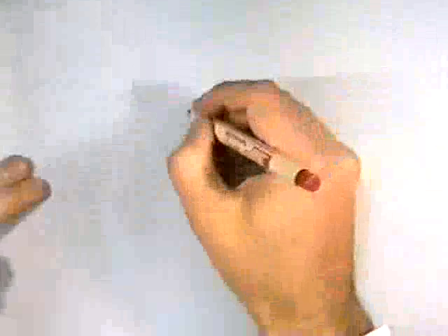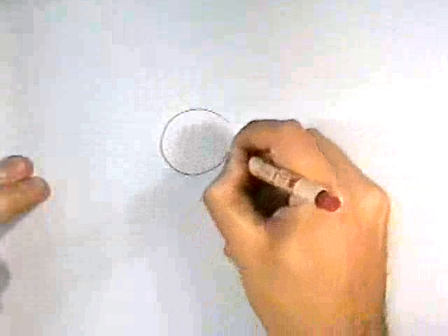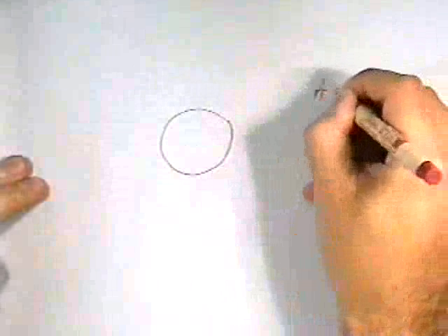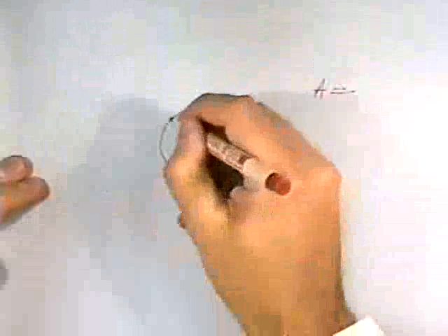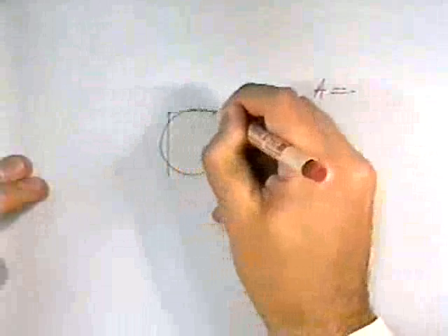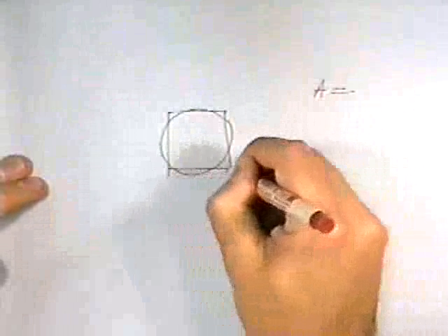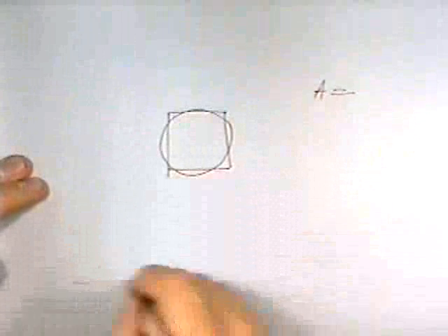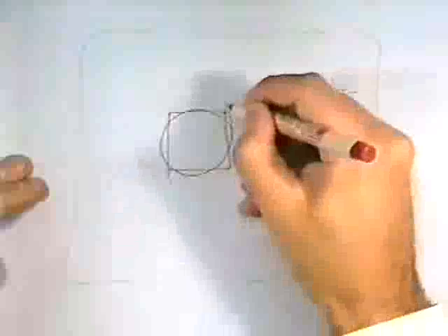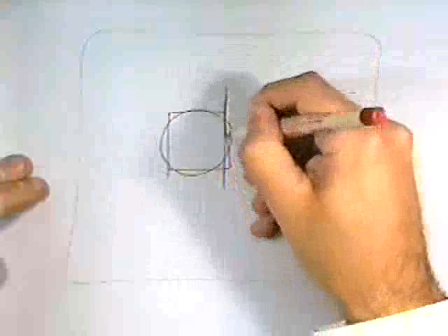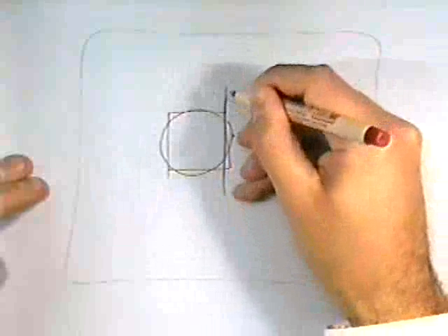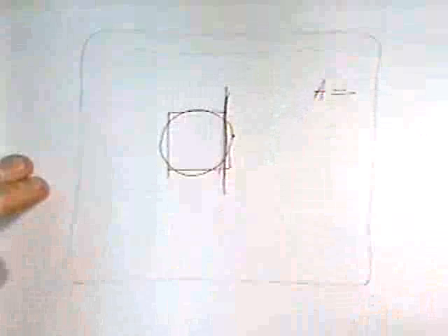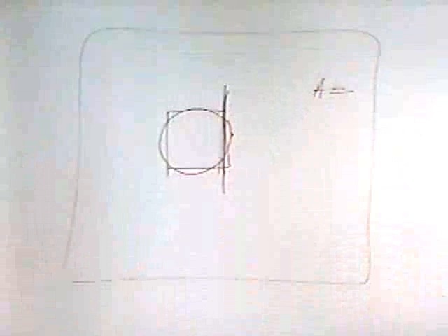Now, I guess the best way to do that is something like this. If I had this circular column, this thing has a certain area. Well, this could be represented by a square column of that area. And if my footing's over here, what I'm saying is that the critical distance is at this point. Not at the end of the circle, but at the end of this imaginary square. That's all we're saying there.